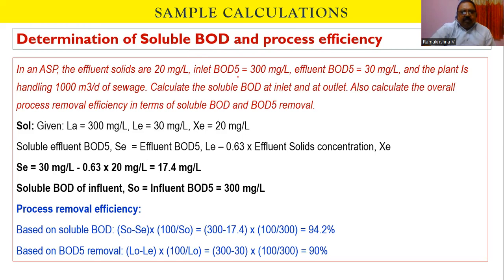the biological treatment, whatever the effluent BOD is, what is going out, it is not actually the soluble effluent BOD, where some solids will also be escaping from the effluent. So that part we have to take care of and calculate the soluble effluent BOD. We will see those calculations in this problem.